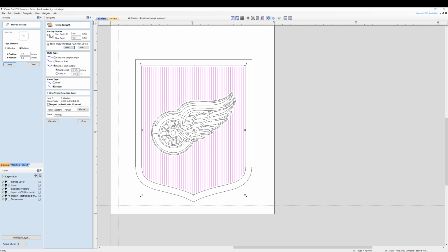So let's press OK. You have some options on this fluting toolpath as far as what type of ramp you want, how long you want the ramp. It's not just a plunge straight across. I guess I could do the exact same thing with the profile rather than fluting, but this just makes more sense to use. I'm going to ramp in 1/8 of an inch smooth ramp on both sides. That's fine. Like I said, this can be completed with the profile toolpath with all these lines. But I'm going to name this toolpath BN250. It's a ball nose 1/4 inch bit, and we'll name this Fluting.